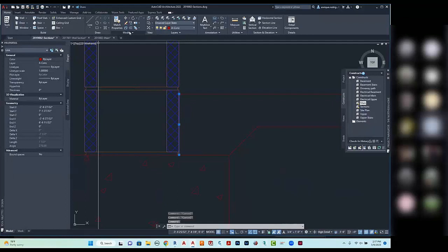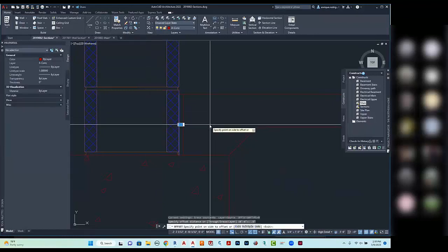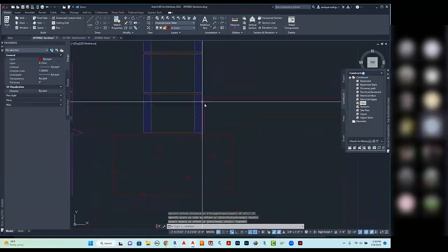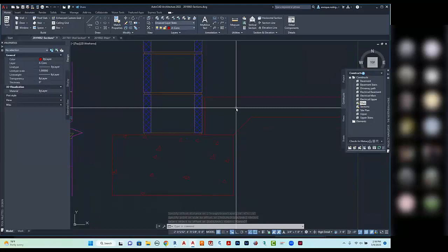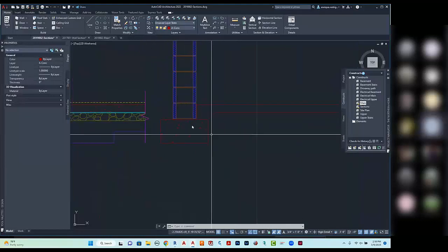And I am going to offset that 1/2 inch in this direction. This would probably be filled with a rubberized strip that would go around there that would be able to compress if the slab tends to expand.